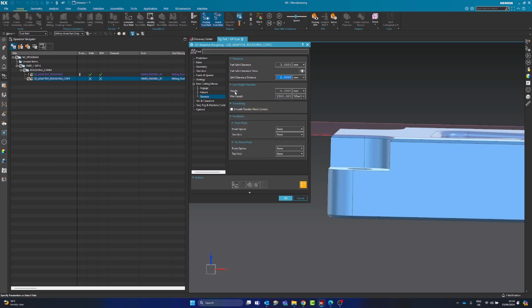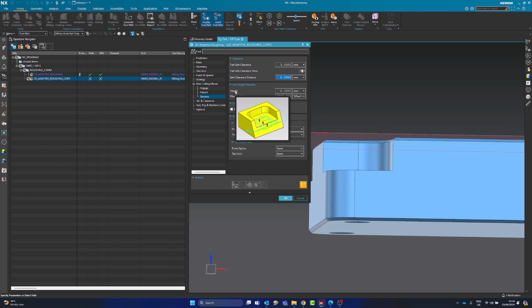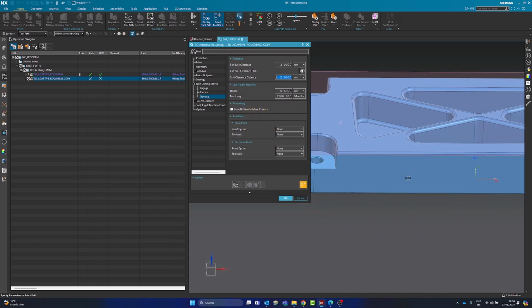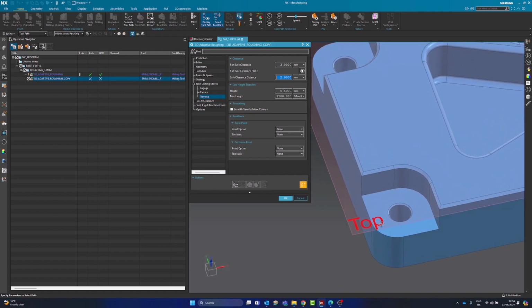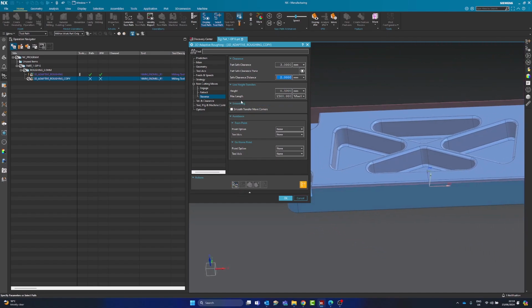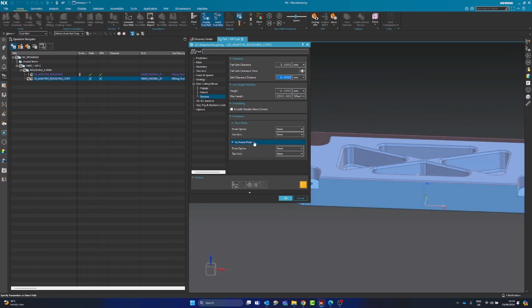So our low height transfers, this is going to be when you're doing trochoidal cuts, and if you're doing like say this sort of pocket here, its first cut at 25% would be like a cut like this, and then you're saying then move half a mil above and wrap it across. So that's what makes it so fast. But you can specify 1 mil, 10 mil, whatever you like, but it's always best to be as low as you can. Okay, so let's generate this and see what we get. We could get some funny things going on here.